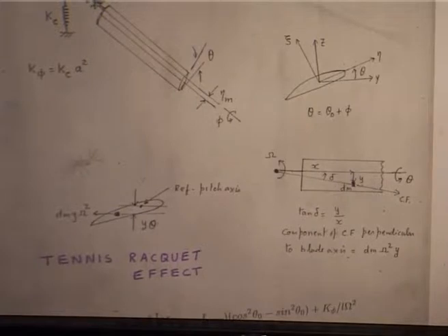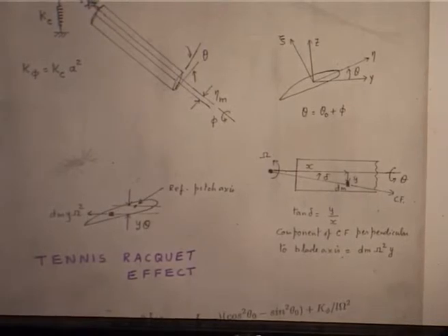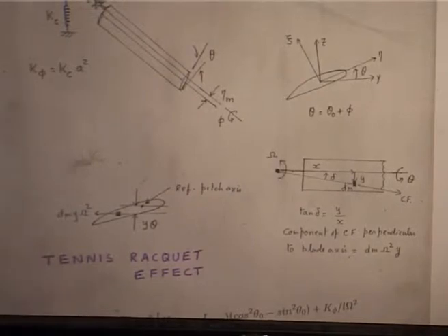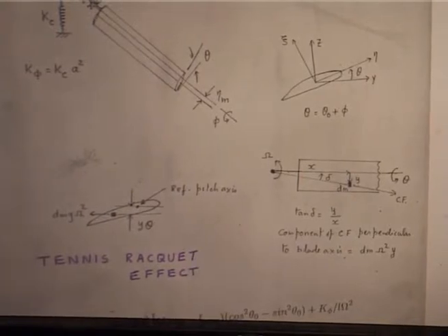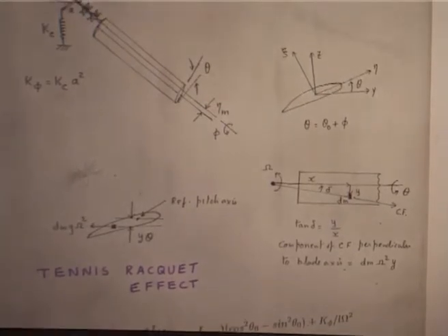and this is the reason why you will see that control system stiffness plays a major role when the blade is operating. I gave you the test data, for I think 5 degrees or 6 degrees, 900 RPM you were matching.